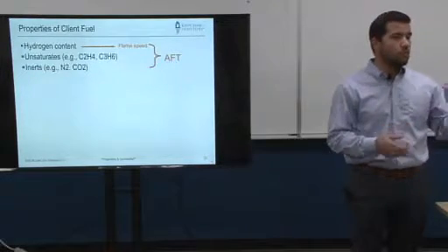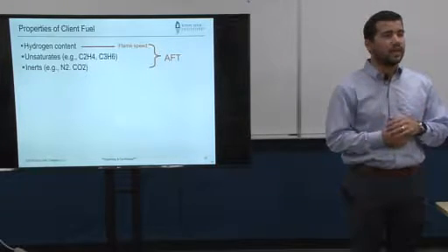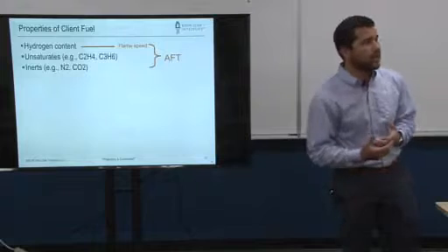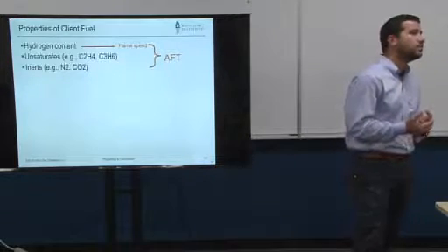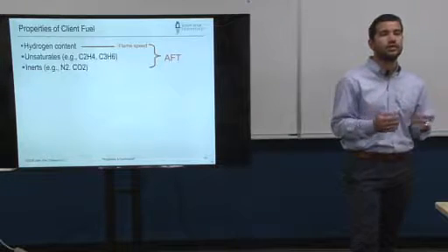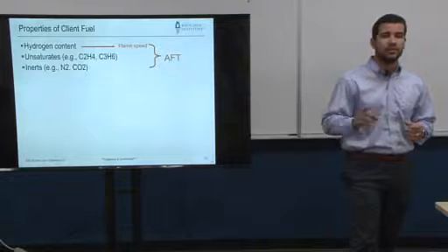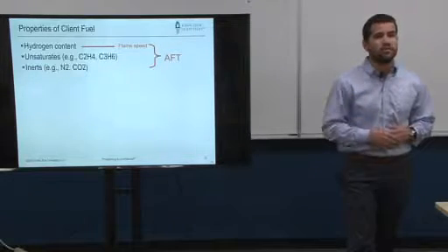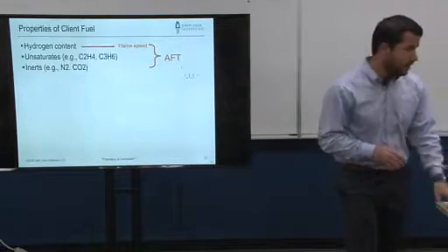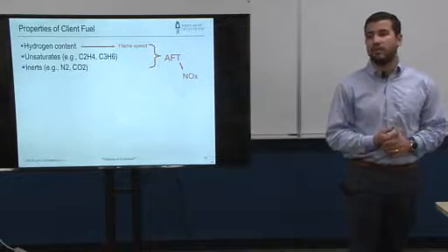And then we look at the hydrogen with the hydrocarbons and inerts to get an idea of the adiabatic flame temperature. And adiabatic flame temperature is just a fancy word that helps us understand the temperature at which that fuel is burning. It's not necessarily the actual flame temperature, but it's just sort of a reference scale. Because the adiabatic flame temperature then gives us an idea of the thermal NOx production that burner will have.